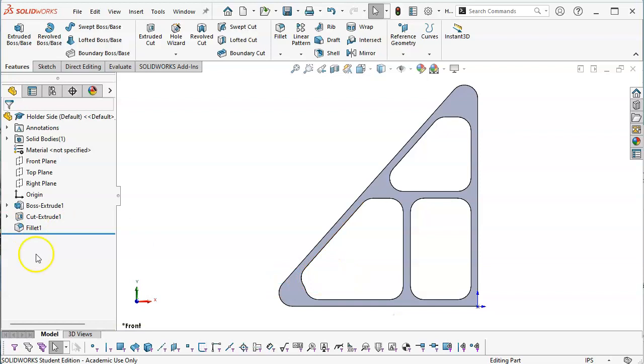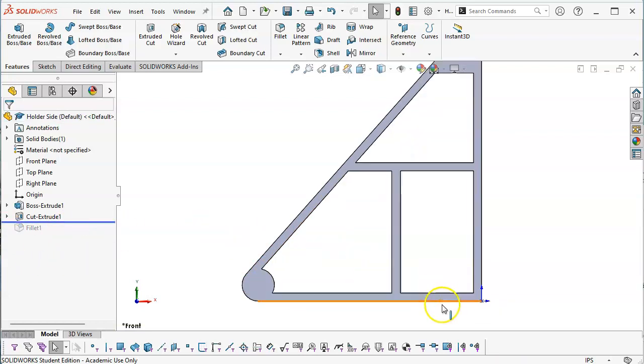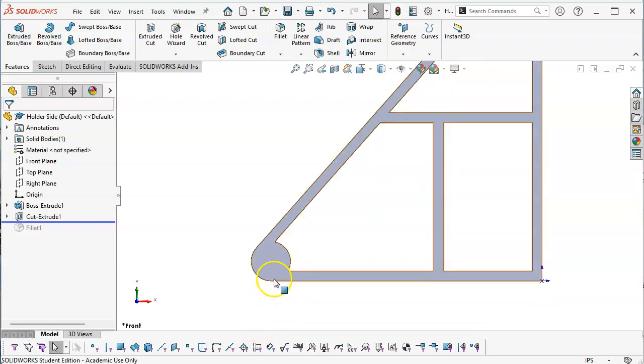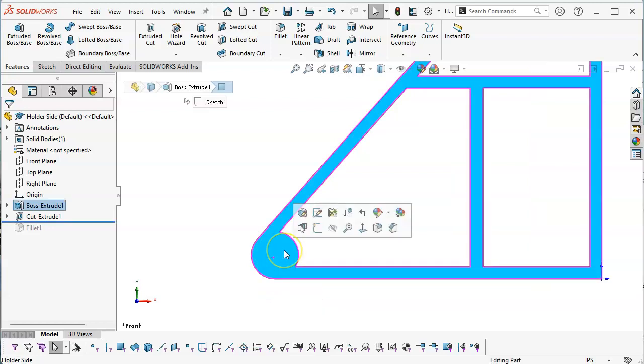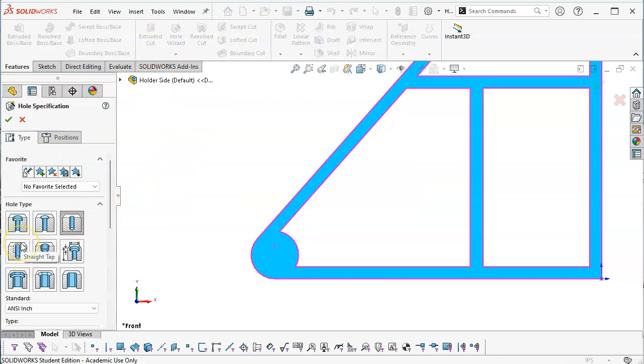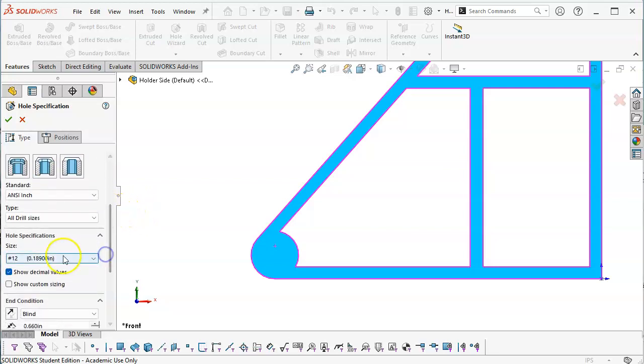And save it. All right, so the fillets look good, but I want to go ahead and put in my hole locations first. There are times where the fillets are changed or they're not tolerance the same, that it would create a little bit of an issue with having things shift. And manufacturing wise, when things shift, it's not usually a good outcome. All right, so hole, simple.